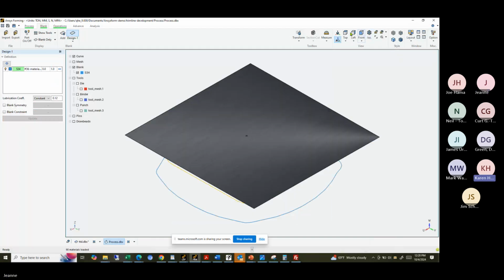And then one of the things, just because of a recent exercise we had to do for a customer, is we're developing a developed blank. So we really need the trim edge to be their final trim edge. And so we're just wondering about the accuracy or the strength of the software to accurately track those trim edges on a custom blank.